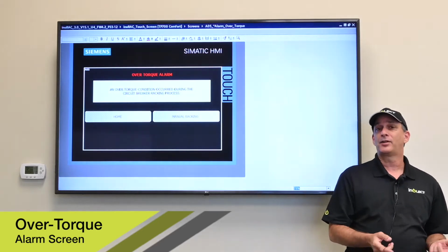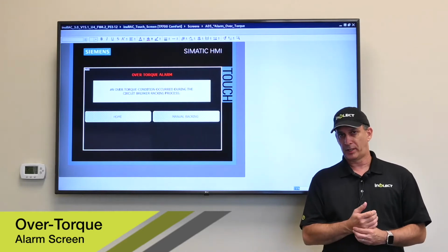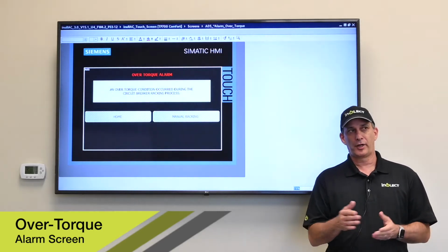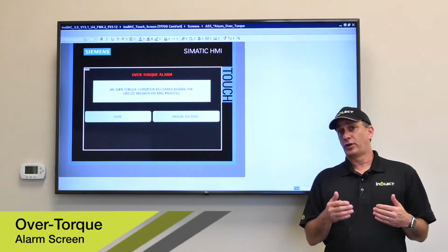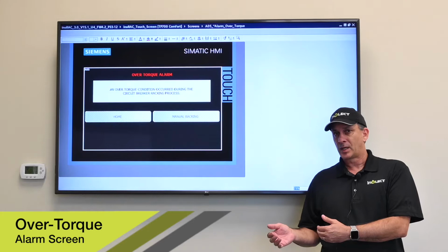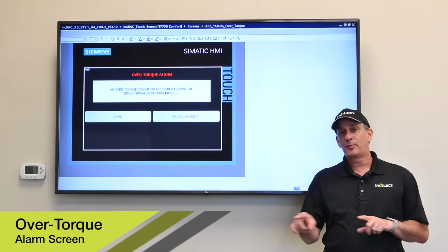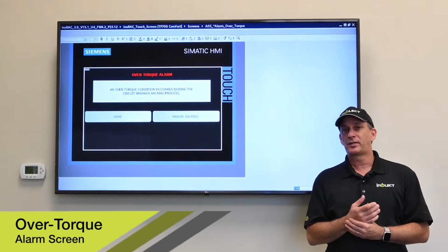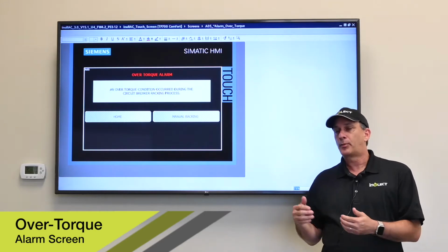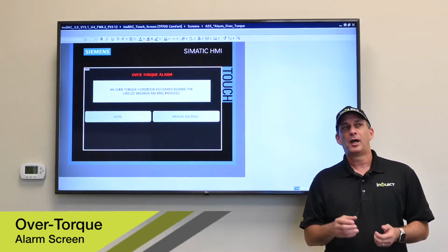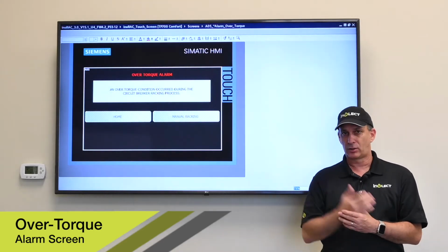So keep in mind that during that racking process, there are variable torque set points that are being monitored. So whether you're in the middle part of the breaker racking sequence, or you're getting close to the connect position, or if you're coming out to the disconnect position, at any point in time, these torque set points can vary because the variable torque programming in the unit is only applying torque at the points where it needs to be raised or lowered.